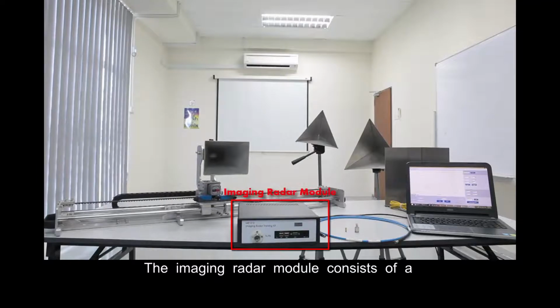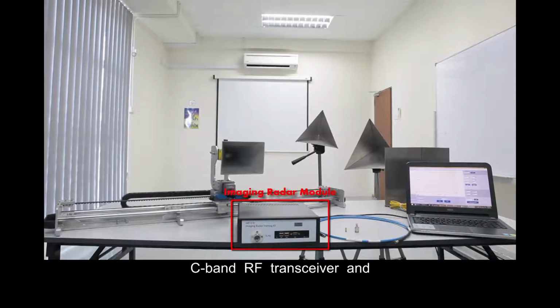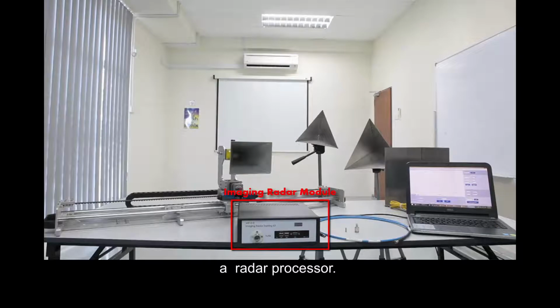The imaging radar module consists of a C-band RF transceiver and a radar processor. The radar processor consists of a data acquisition unit and a high-speed single-board computer for raw data digitizing, as well as SAR signal processing.